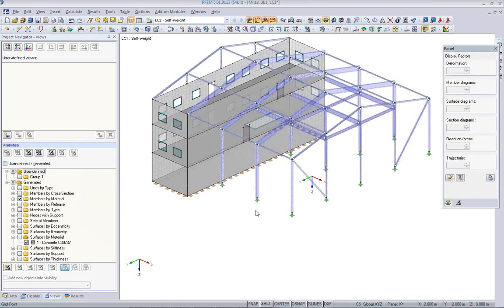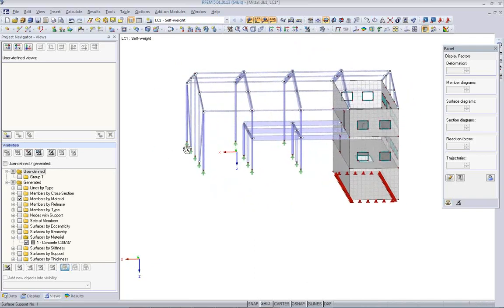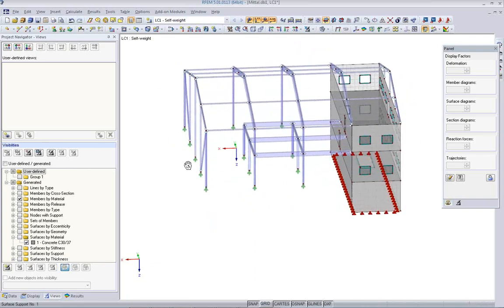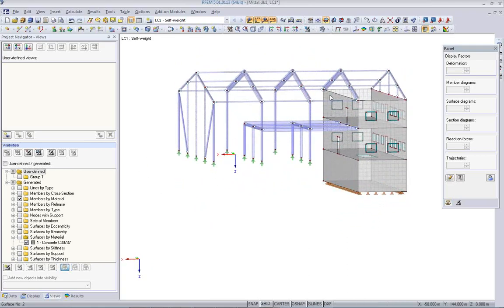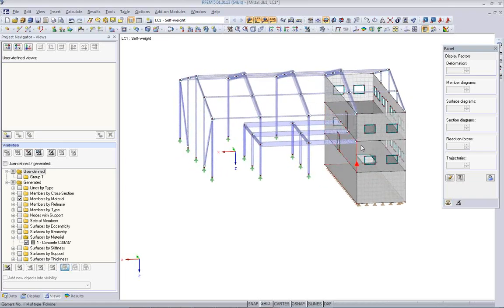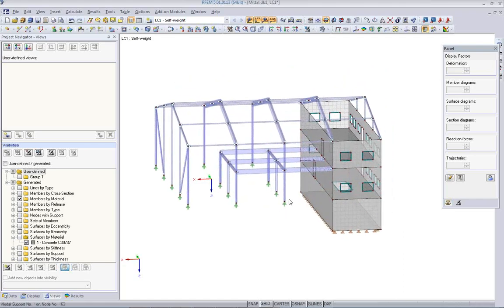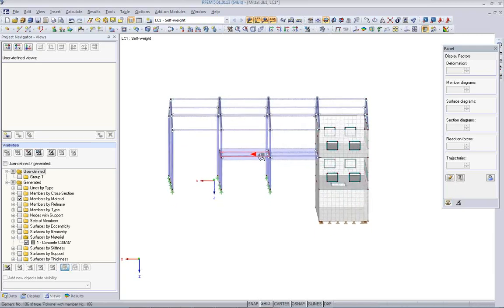First of all, maybe I should check another thing from the structural point of view. I need some bracings here in the roof. Typically, we have some bracings here. The first level of the grid is supported horizontally by the concrete part here, but the roof structure is maybe a little bit unstable, and I would like to have a bracing here.